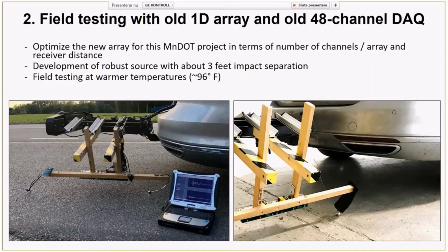The array or the microphones itself just look like an electronic circuit board, so there's no close-up in these photos, but you can see the main arrangement in this setup with 2 sources. And the reason why we're using 2 sources is because sometimes the array is not completely leveled with the pavement surface. And so if the array is not completely leveled with the pavement surface, we will get apparent velocity, which is a little bit biased because of the tilting of the array.